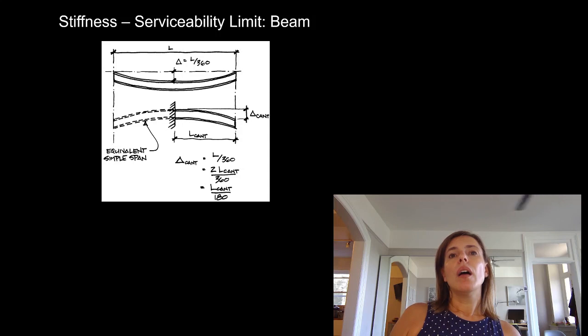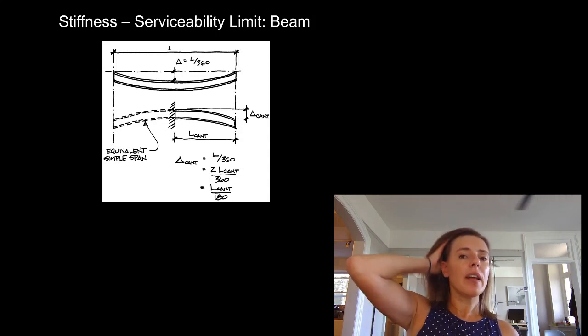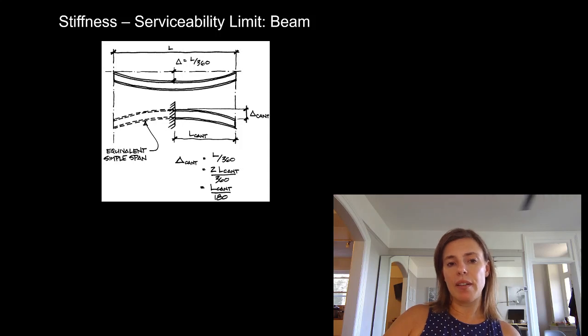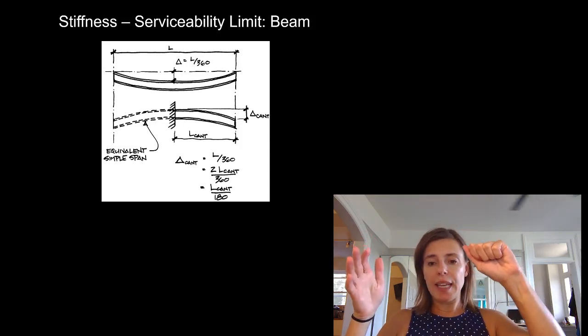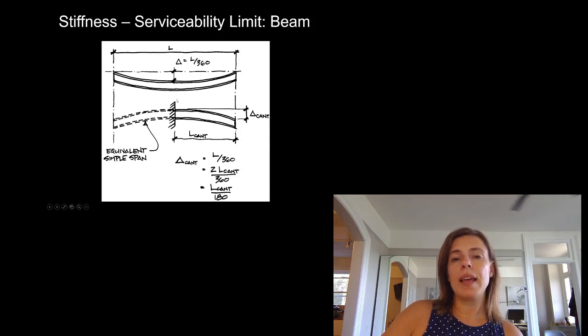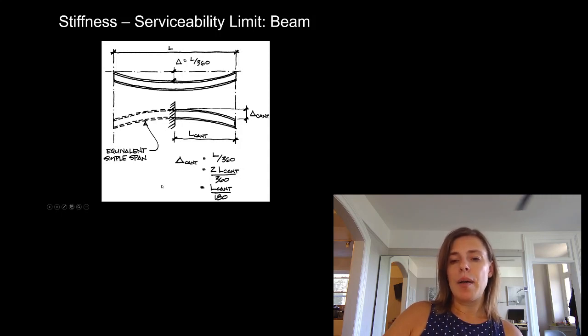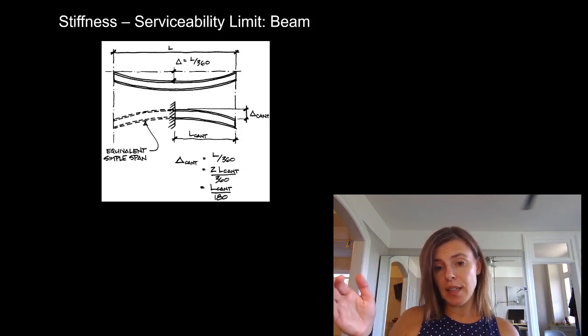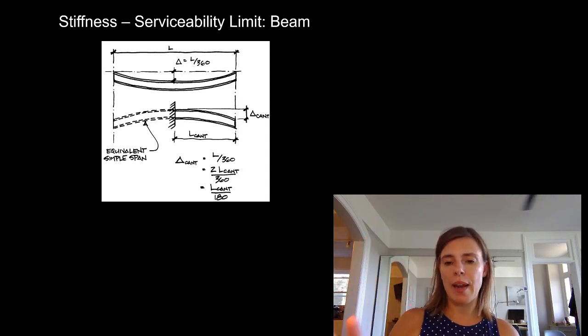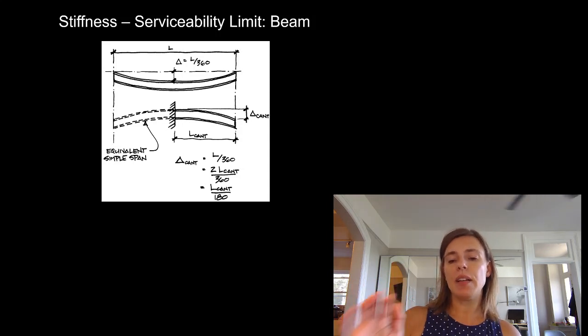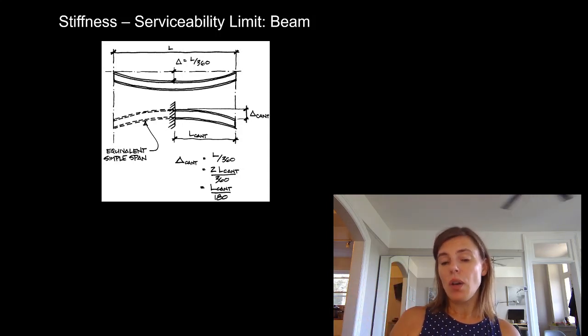If we're talking about a cantilever, we have the criteria. So if we have something that is rigidly connected at the end, and we're going to see that it's drawn like that, we only have to use half of the deflection criteria, which means we can allow it to deflect more. But not really. If you drew this curvature, you can see where we're coming from. What we're really saying is that we're using half of the length of something. So basically for you, if you see a cantilever, and we're going to talk about cantilevers going forward, so don't panic about that too much, it would be half of the criteria. So if it had been L over 360, we're going to use 180.